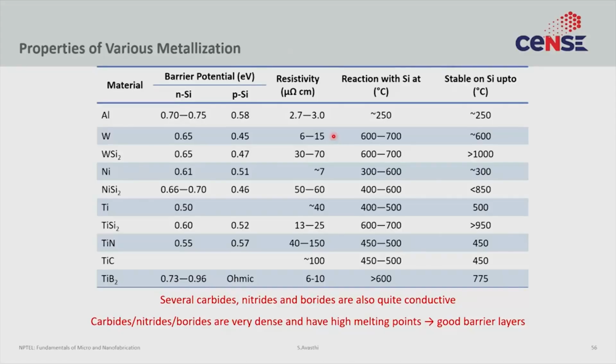The reaction between tungsten and silicon to form a silicide happens at 600-700 degrees C, partly because tungsten is a high melting point material, it sort of diffuses less, etc. So, it means that you can actually make stable tungsten silicon junctions up to 600 C. Tungsten is often used for military hardened or space hardened devices for this reason. It's stable up to much higher temperature.